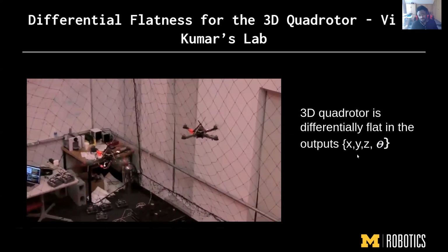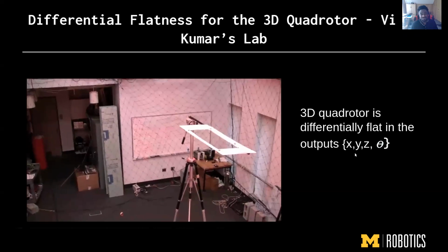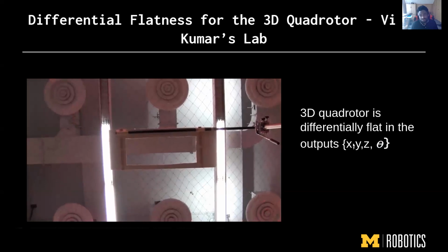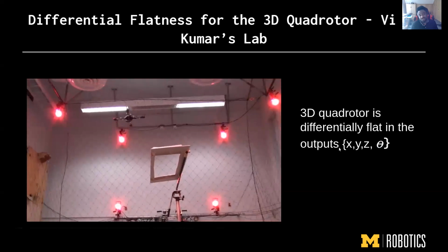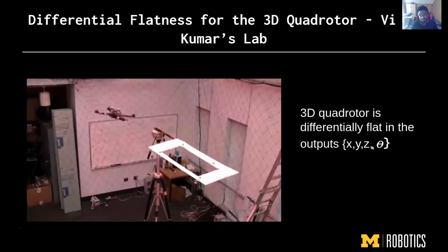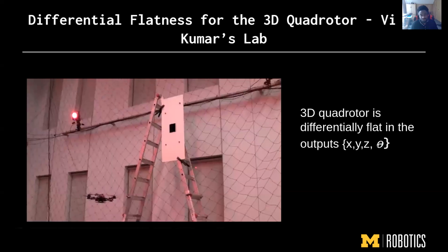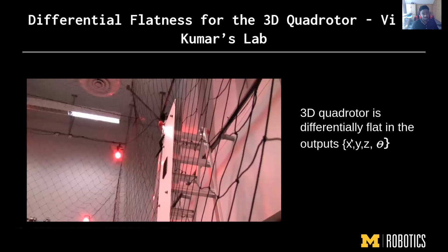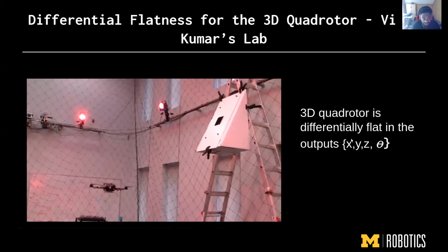You could even use a regular motion planner like, say, RRT to plan this XYZ trajectory. You might not even need trajectory optimization. But then the nice thing is that once you have this trajectory, we can then use the system dynamics equations to infer the control inputs to each of the 4 motors, as well as the roll, pitch, yaw orientations that are needed to perform these aggressive maneuvers. And that's ultimately what they actually use in these really nice demos.